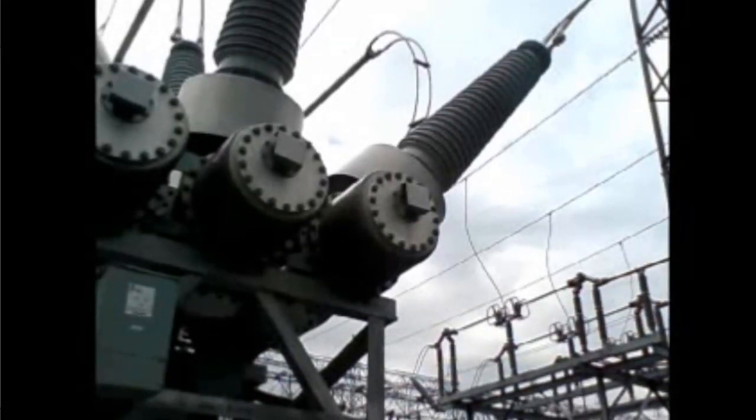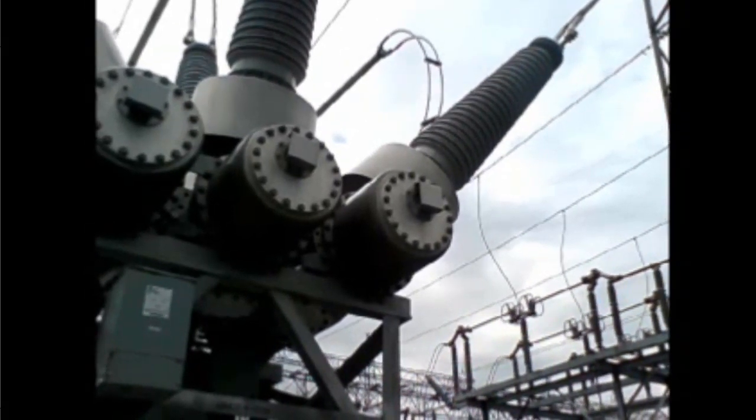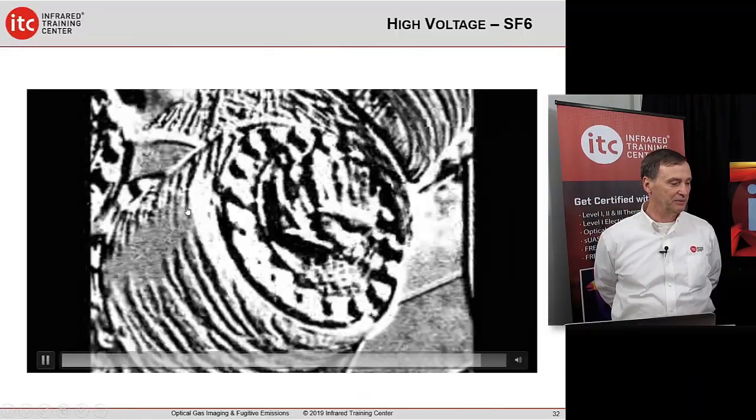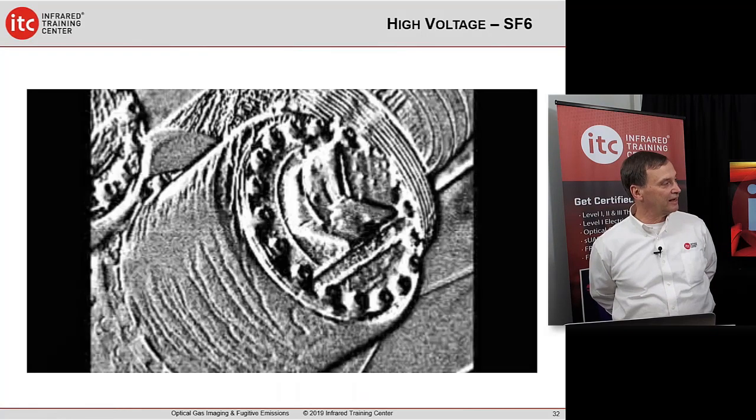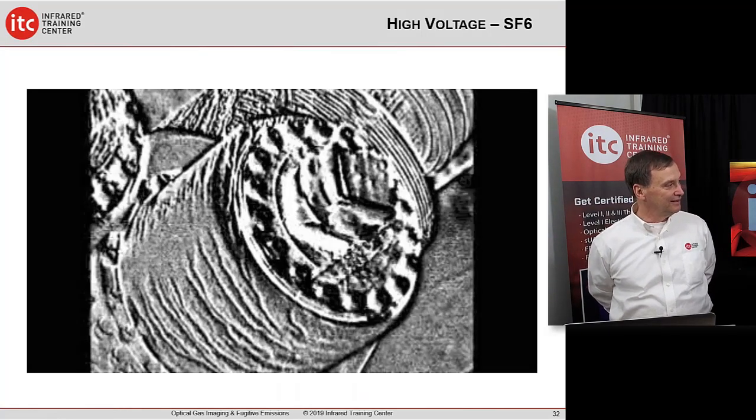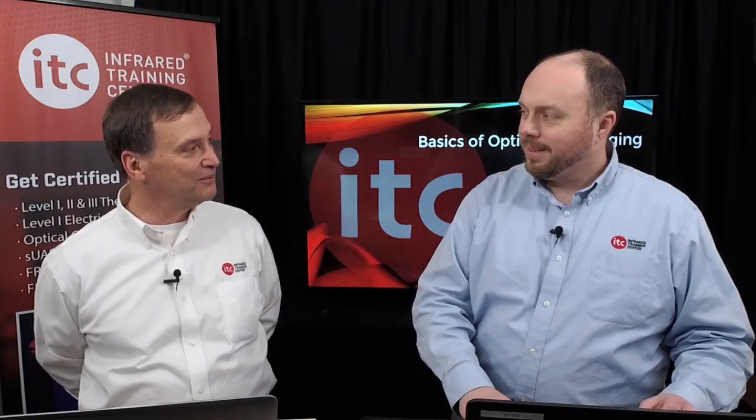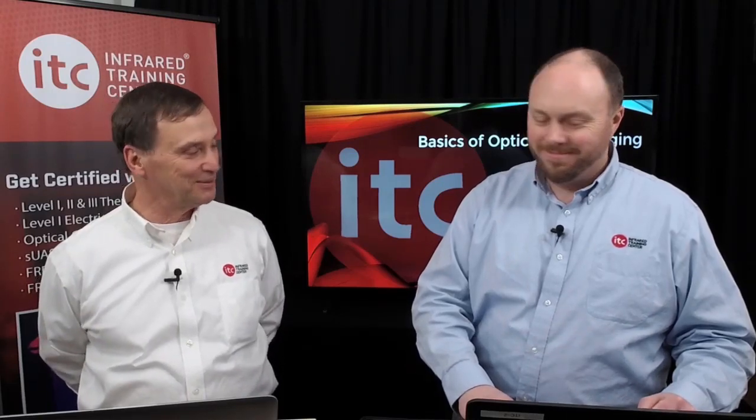And you cannot see the leak. None of these leaks are visible until you turn on the IR camera. And here, that's just in the high sensitivity mode, the HSM. Normally, I use a tripod. You can see the breakers up through there. It was the center one. Normally you would use a tripod, but the static voltage was so high in that switchyard that day that we couldn't. It was wrecking the camera.